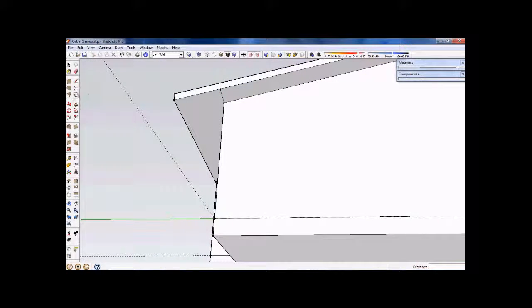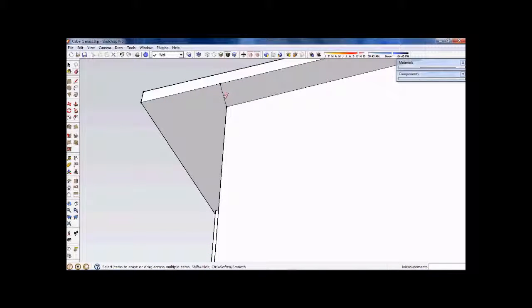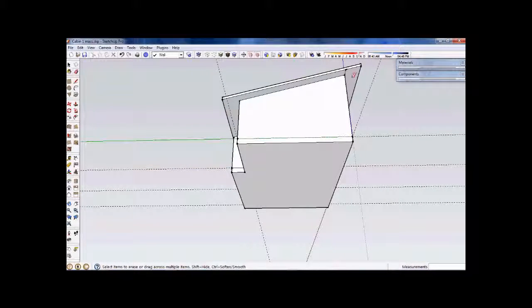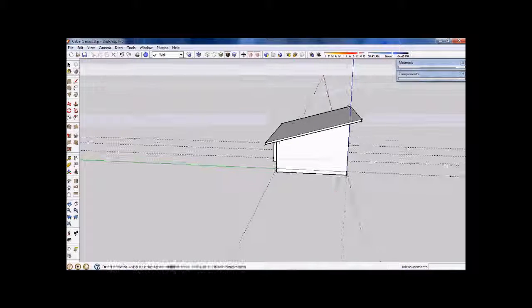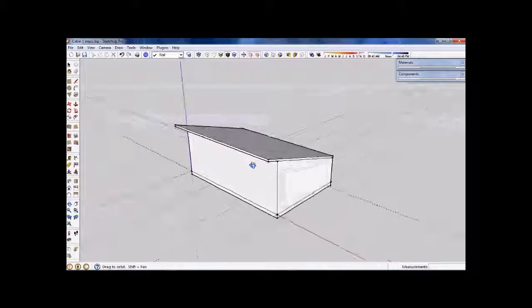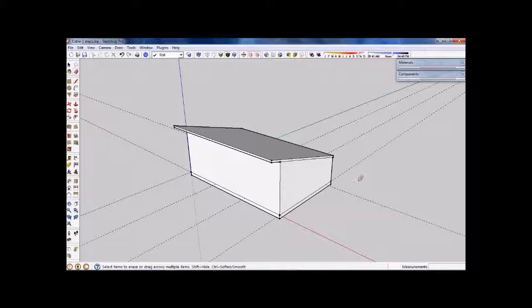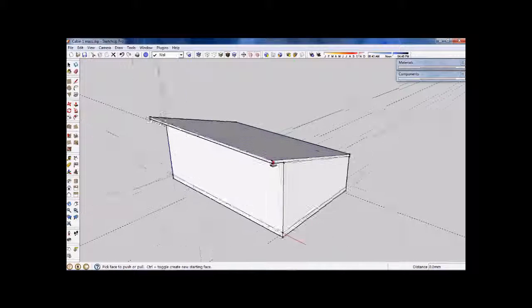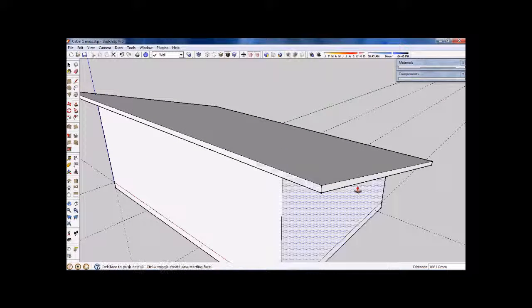And do the same around the other end of the building. We will have a carport out this end of the building that will be 3 meters wide, and I'll probably assume, let's sail the wall past another 150 past that point. So we'll push-pull this gabled end of the building out 3150. So push-pull, drag it out, let it go, type 3150, press enter, and that's that extent of the roof fixed up also. But I'll just tidy it up a touch.